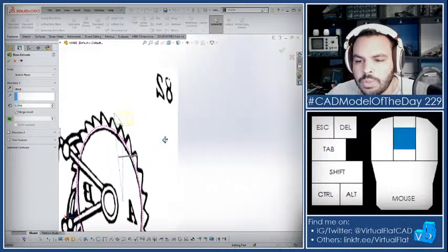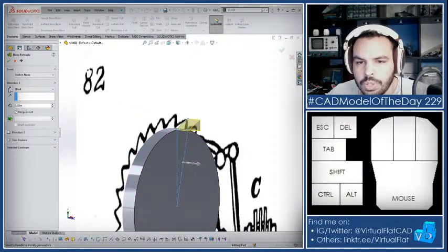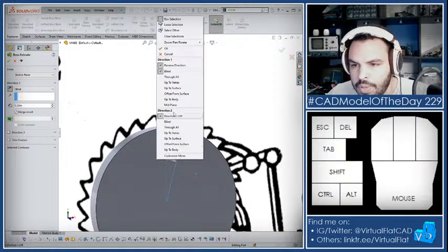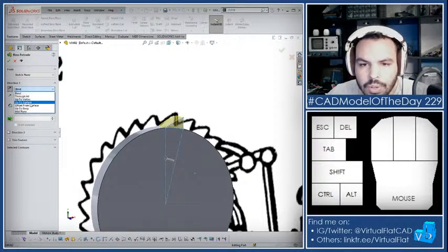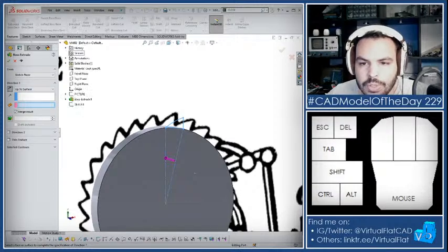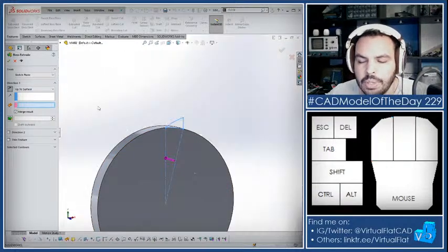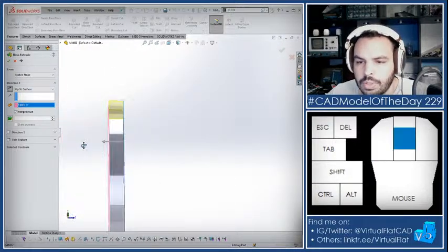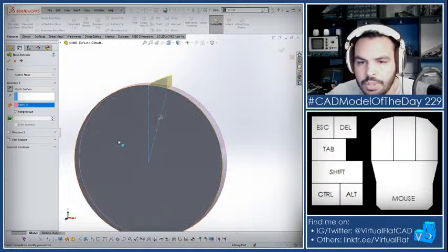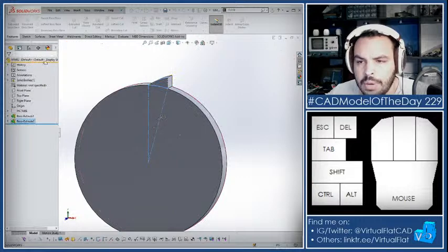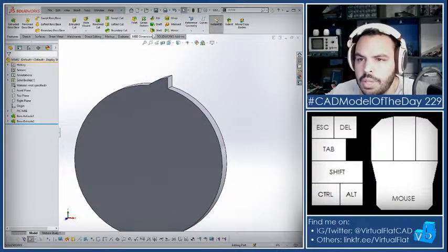And let's extrude. And let me see if I can get a select other here for up to surface. Yeah, and this whole thing's blocking me. So if I ever decide to change the thickness of this, it'll update. So now I have to pattern. A lot of the times these patterns like to fail. And if it does, I'll just unmerge it and pattern it as bodies.